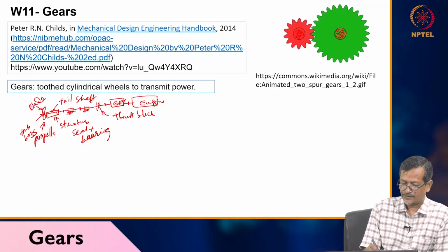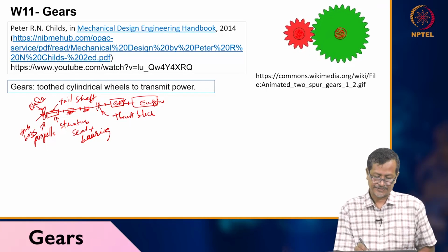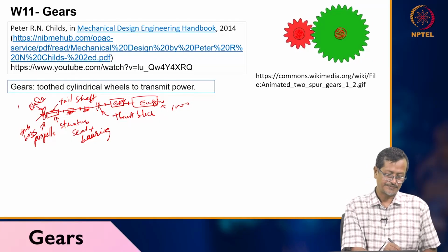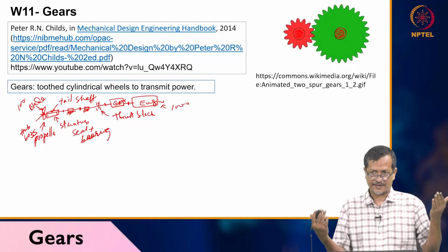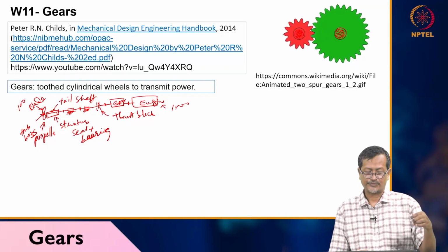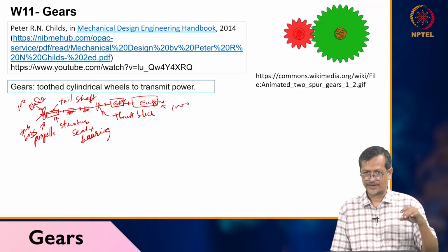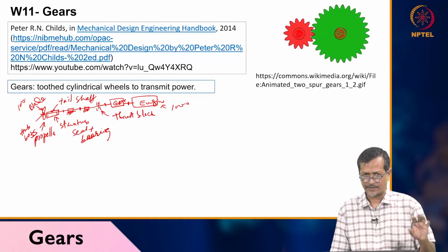And when we are talking about the gearing system, normally it will be a gear reducer. Why gear reducer? Engine speed is normally, say, 1000 rpm, and blade speed, let's say 100 rpm. So 1000 rpm engine speed, blade speed 100 rpm. So you have to reduce the speed, otherwise the system will not work. Your propeller will be at too high a speed, and at that speed there will be cavitation and other issues. So we do not run the propeller at very high speed; rather, around 100 rpm will be optimal.